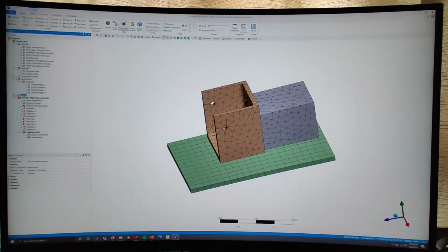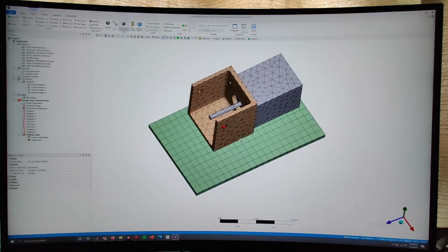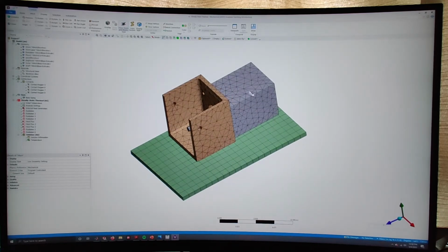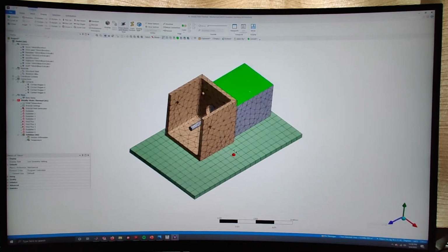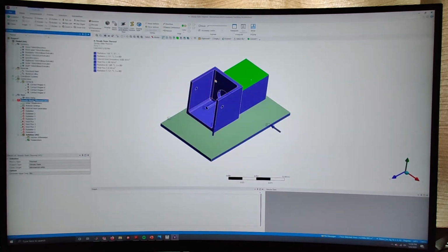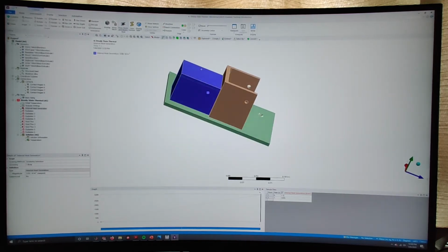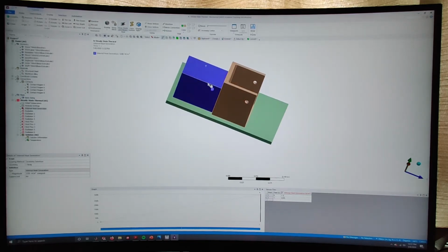Then we're going to run in here this mesh. Obviously, you can select a tighter mesh, but for thermal analysis, this is perfectly fine. The engineers I've worked with at Lockheed Martin, they would actually just run the motor here as a single element, so this is overkill, honestly. Then we'll come in here, for the steady-state thermal. You can insert your boundary conditions, your forcing functions, what have you. So I'm interested in a heat generation term for this motor here. I know this is 0.8 watts because I've already done some efficiency analysis on the motor that we were interested in. And then you can bump it up to see what it should be. Given this geometry, it wants it in watts per meter cubed, so you just have to size it according to the geometry.